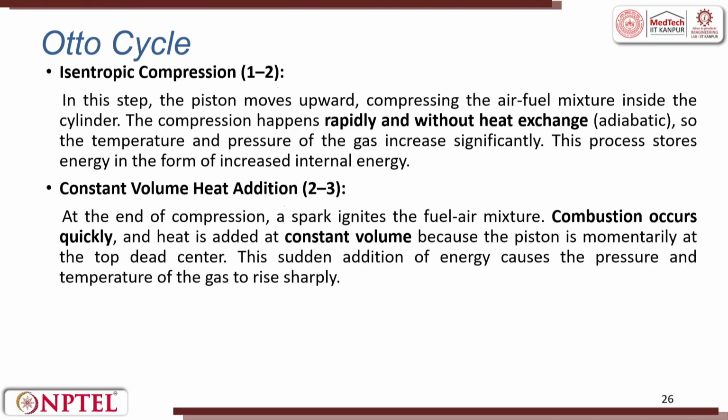In this system, the piston moves upward, compressing the air-fuel mixture inside the cylinder. The compression happens rapidly and without heat exchange, so this is an adiabatic process. The temperature and the pressure of the gas increase significantly. The process stores the energy in the form of an increase in internal energy.